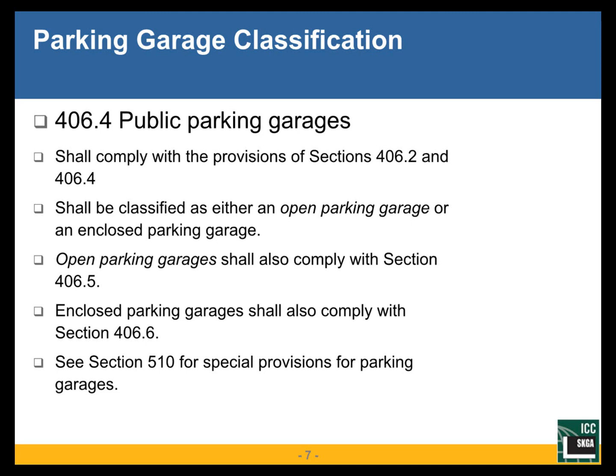They're classified as either open parking garages or enclosed parking garages. And the section in IBC that covers open parking garages is Section 406.5. The enclosed parking garages comply with additional requirements in 406.6. And then there are parts of Section 510 for special provisions for parking garages.